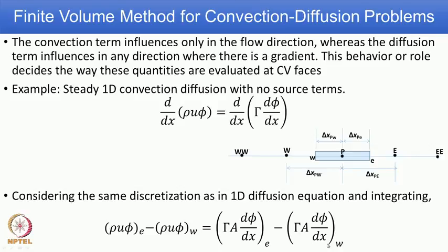So, you understand we have additional complexity when we deal with the convection term. If this convection is written for, say, u as the variable phi, then it becomes rho u u, and rho u evaluated at the east face and west face.